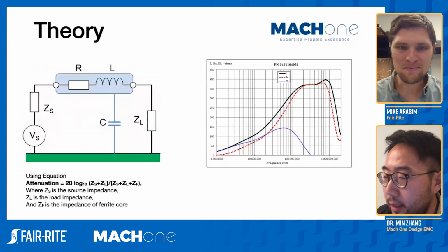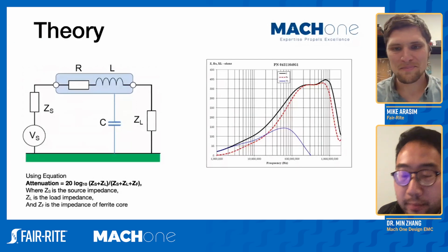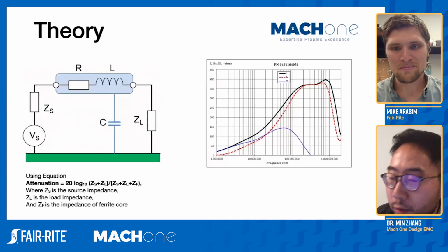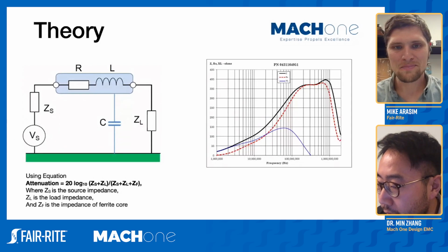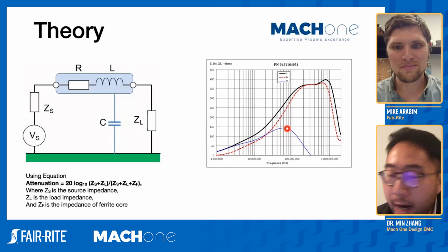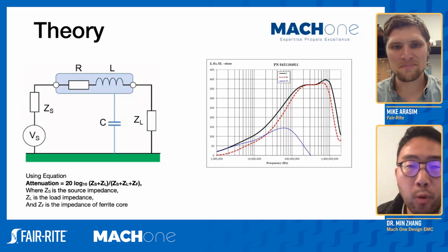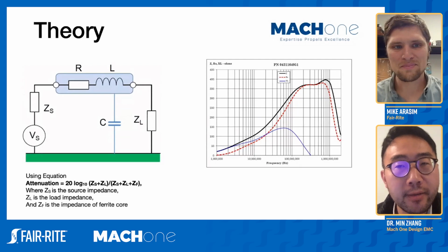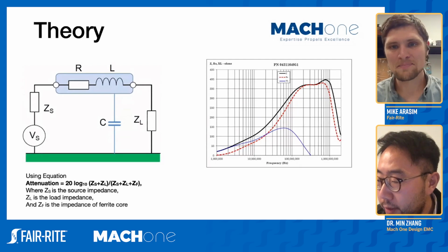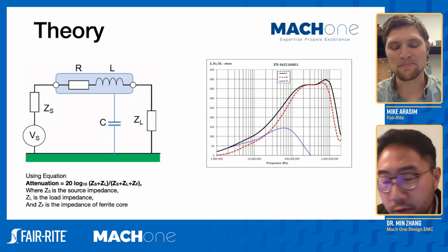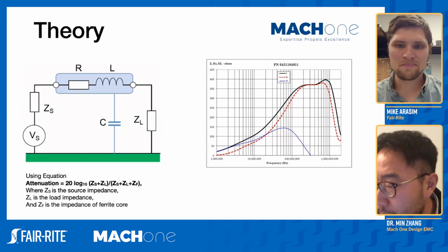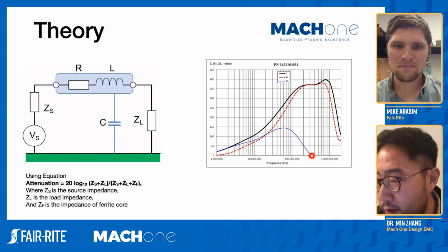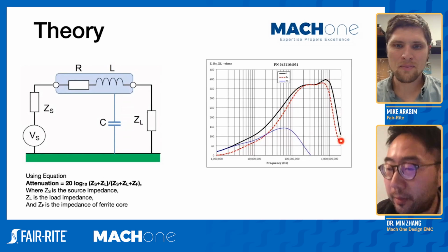Yeah. I guess for me as an EMC engineer, I never really check the inductive curve because, as you said, I treat a ferrite core as more like a frequency dependent resistive part. But is there any occasion where people actually wanted to use this inductive characteristic curve, or most of the time people just look at the resistive curve or impedance curve?